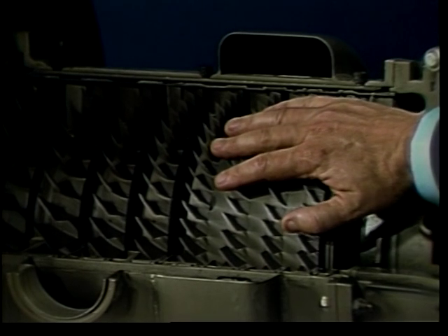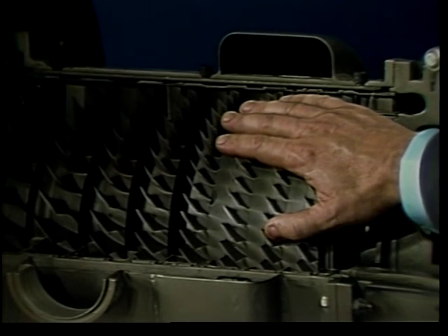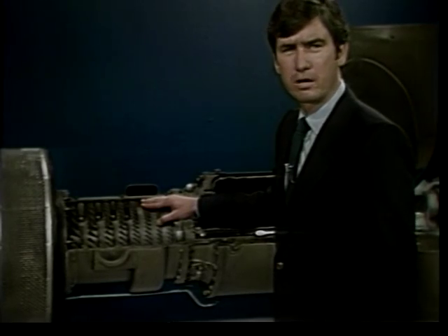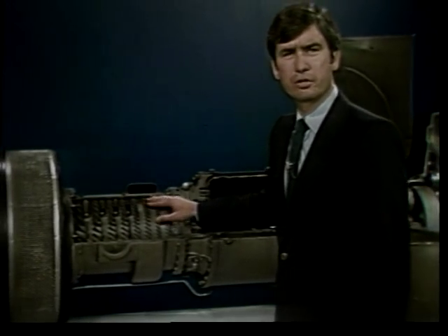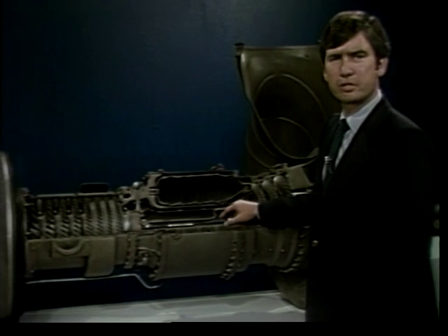The rear stages then become choked because of their inability to move the large volume of air out of the compressor. The resulting surge condition causes the turbine to heat rapidly to an extremely dangerous level. This will severely affect the turbine components and decrease the engine's lifetime.